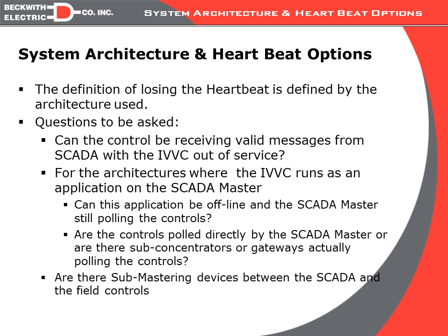And so that adds a bit of complexity that is much easier to handle in the central master approach. So you may have a combined approach where you're running in a distributed or a substation-based approach, but if you have sectionalizing, it may fall back to a central approach.